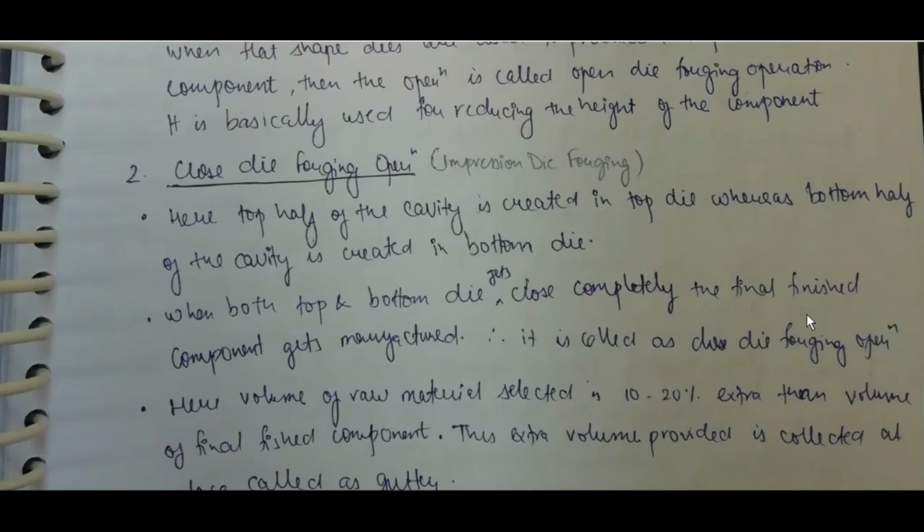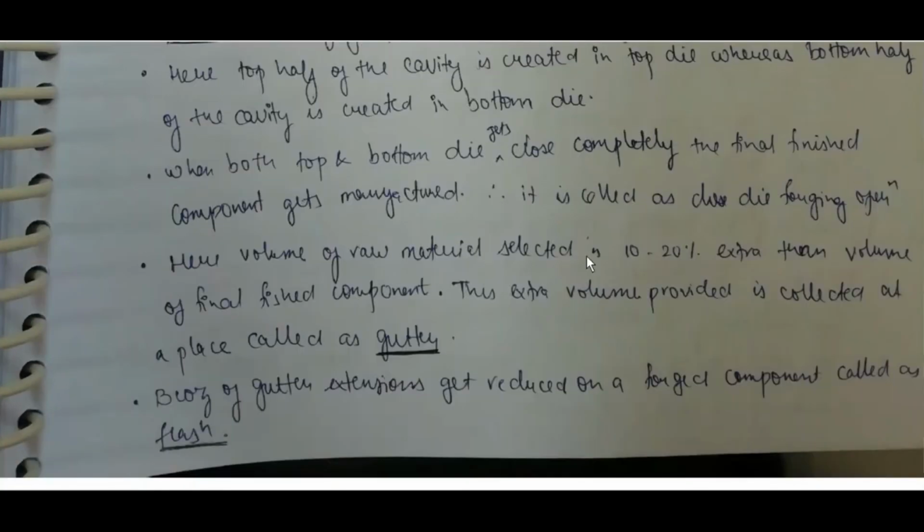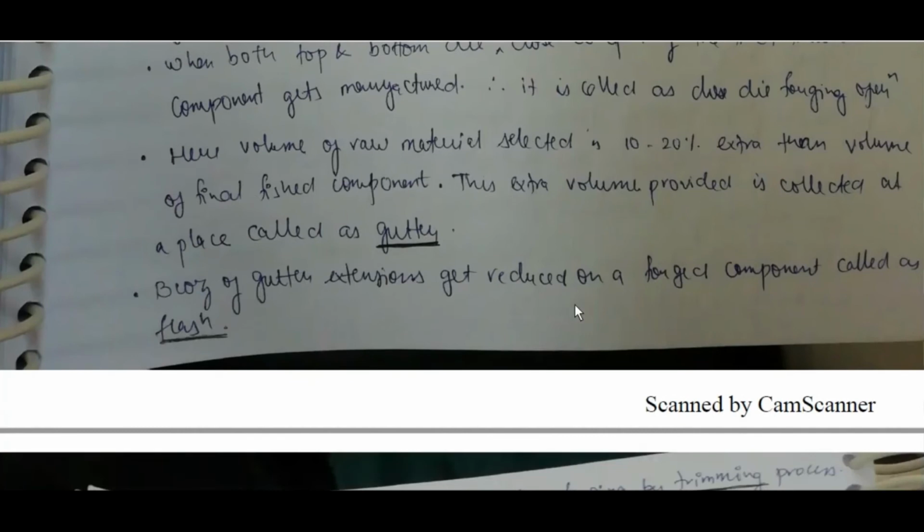Blocking or swaging: producing a nearness to the final shape of the component in closed die forging is called blocking or swaging. Finishing: producing the exact final shape of the component in a closed die forging operation is called finishing operation. Trimming: cutting the material along the entire circumference is called trimming operation.